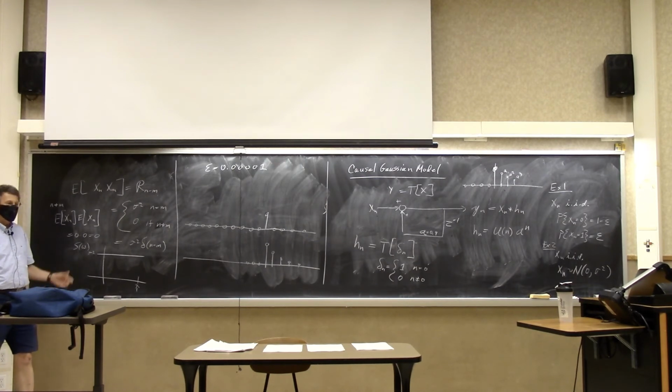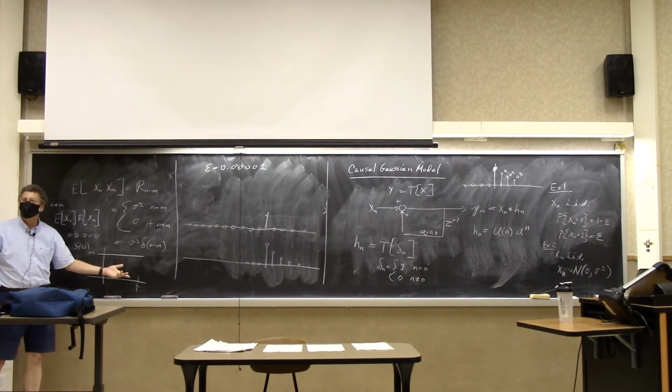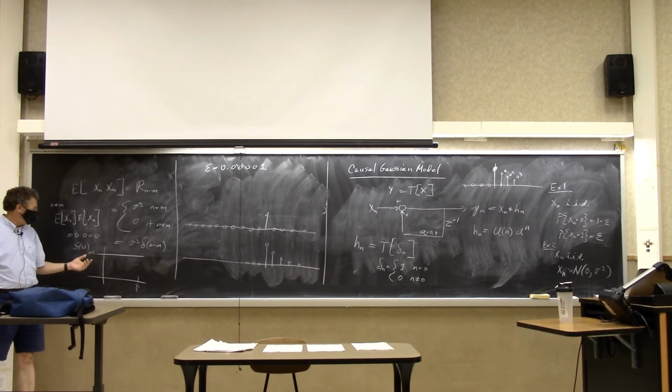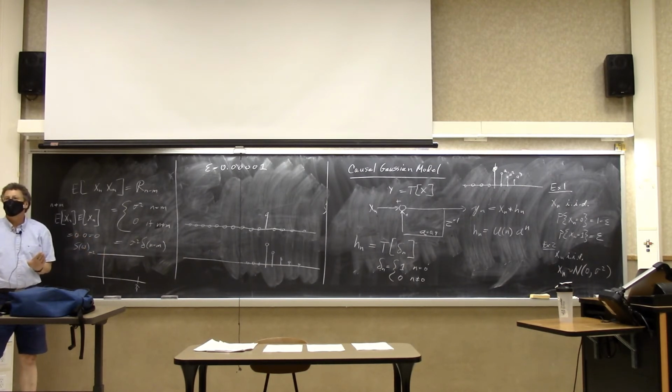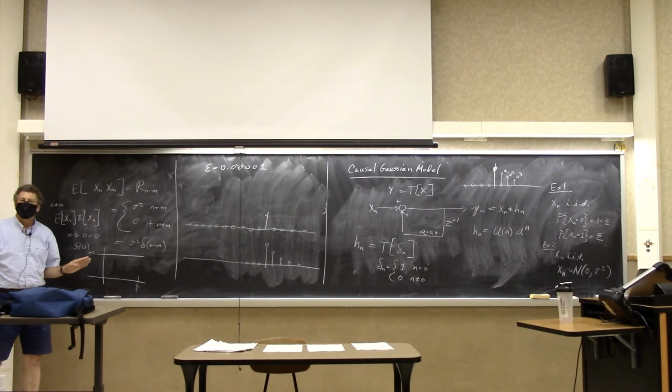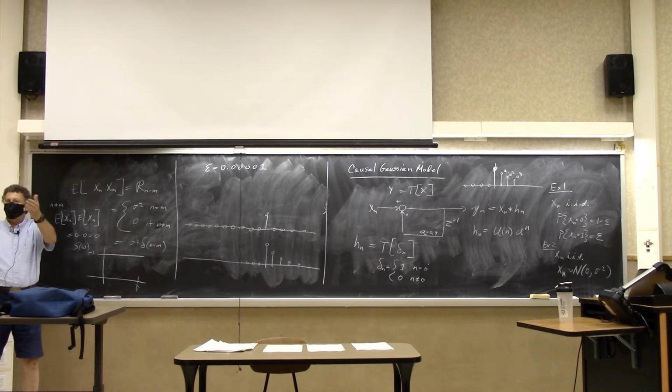So there's also things called pink and blue noise. Pink would mean that the noise was skewed towards the low frequencies. And blue noise doesn't exist in analog, but it exists in digital. Blue noise you can't have in analog because we require that you have infinite energy, because you have a spectrum which is high pass. That means it has energy that goes up to infinite frequency. It never happens.